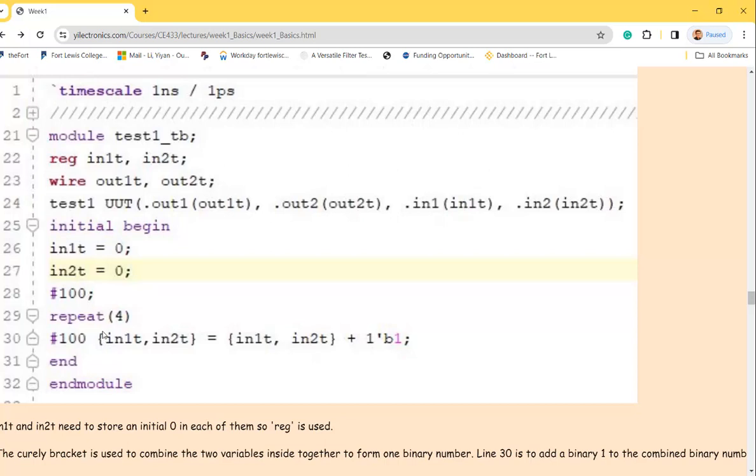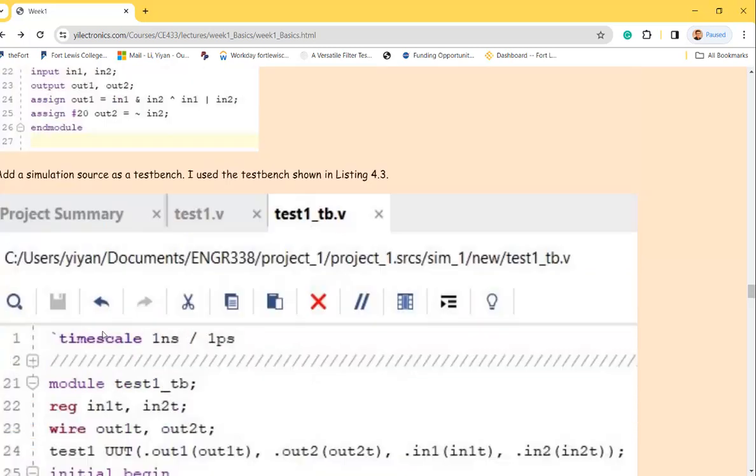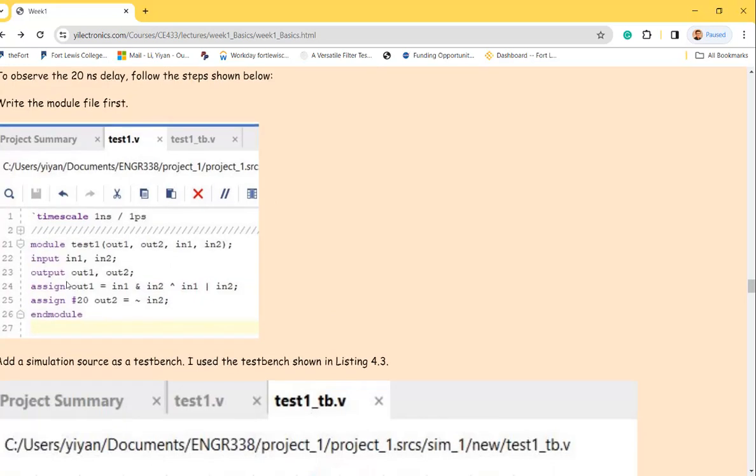So the statement in the test bench is for simulation purposes. You're actually writing something like SPICE code for simulation. It's not a synthesizable hardware or digital design. Probably you are thinking, hey, you just talked about digital designs, everything is implemented on the hardware once, right? Why is it able to repeat so many times? This is just simulation. It's not synthesizable. You cannot make a hardware just based on this test bench simulation code. It's only for simulation.